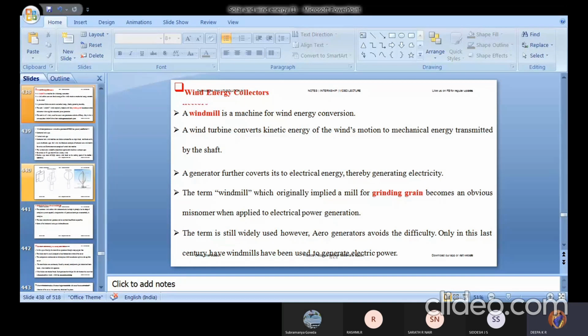Then, if the blades are made up of metal, flexing reduces their fatigue life, with the rotor and tower also subjected to the above loads, which may cause serious damages. It's based on the capacity. People using metal blades, of course, weight wise it is still heavier as compared to the other materials which are used for making the blades. And it is going to reduce the fatigue, in the sense the lifetime of the system.